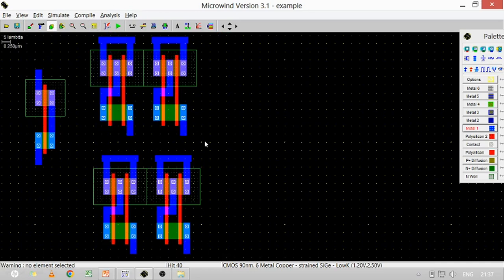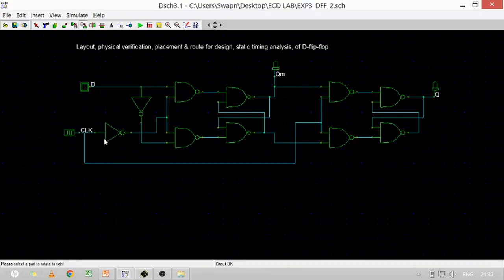Now we have the common clock, and we have D and S and R. Here we find this is S, or we can say D and inverted D, or S and R, whereas the clock input is the same. We have one clock, and we make it one input of both NAND gates N1 and N2, taking it common.